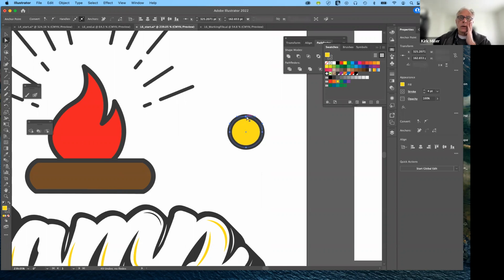I'm just going to click up here and hold down the Shift key as I move it so that it moves straight up, like so. But you'll notice by default, this is a curved point. And later on, you may want to keep it curved. I can click and drag and move it like so, and we can do any number of things to it to customize the curve.